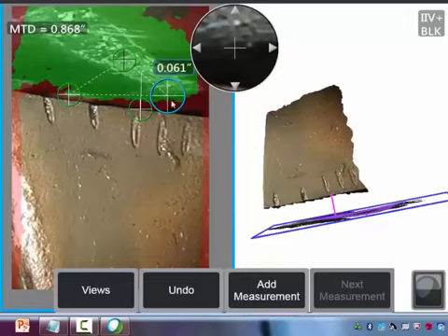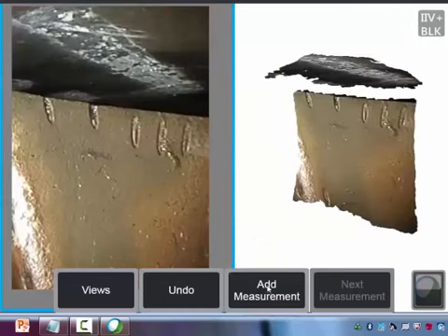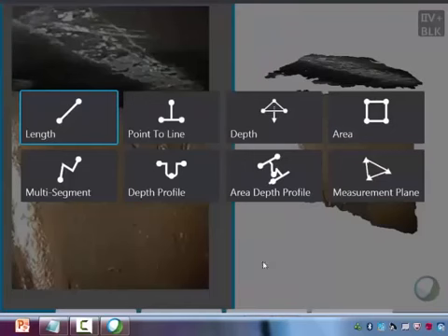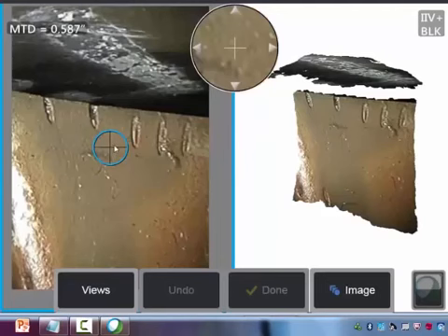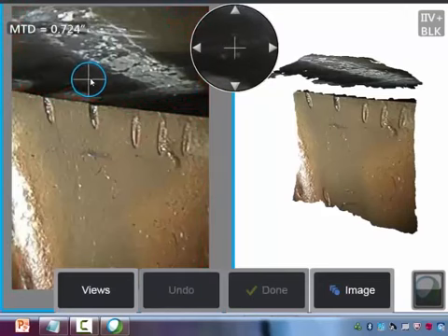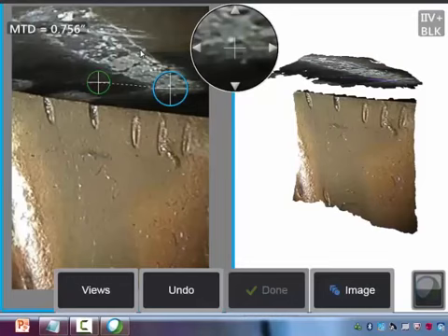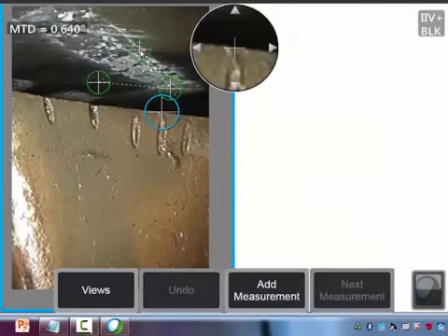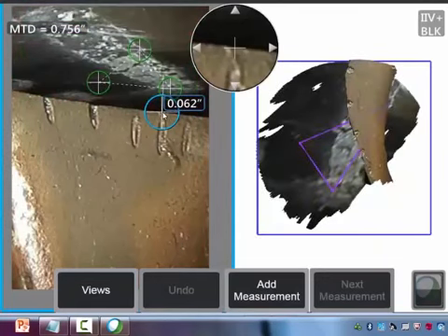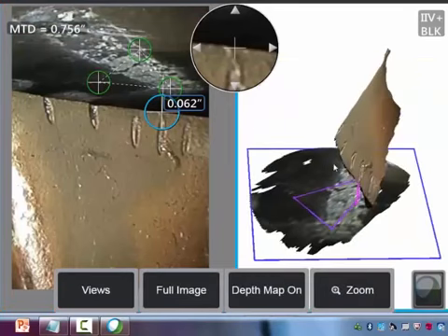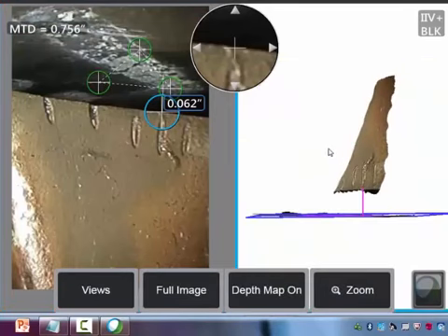And we talked earlier about how the Depth Assist feature can help you hit the deepest point in an indication quickly. Depth Assist can also help you perform these tip clearance measurements more quickly. In this case, when I drop the third cursor on the shroud, the fourth cursor automatically appears at the edge of the blade. This can be a really nice time saver for the users out there who perform a lot of these tip clearance measurements.